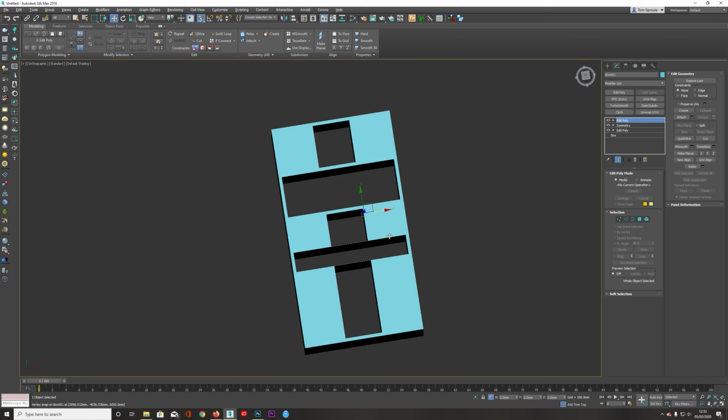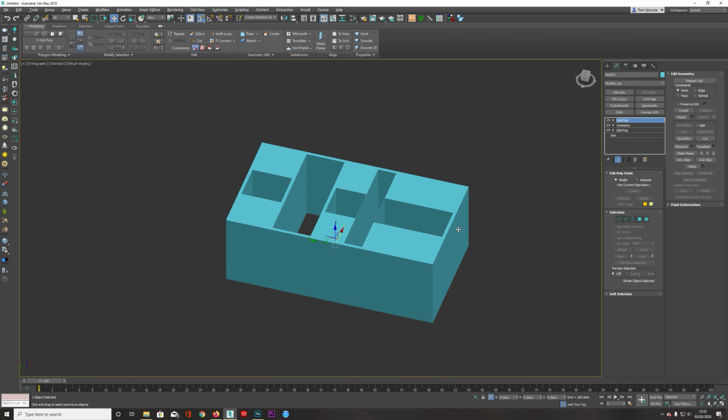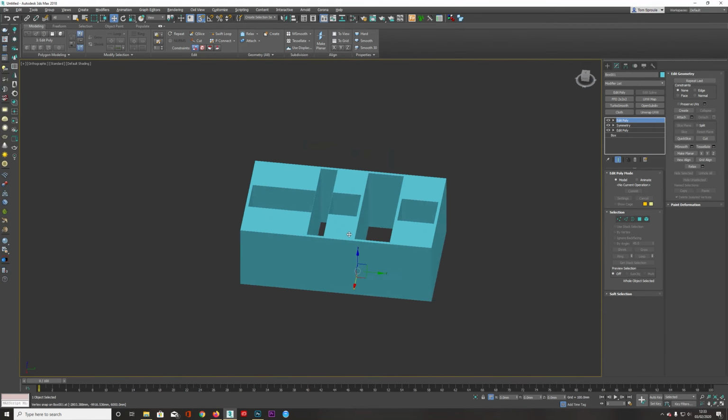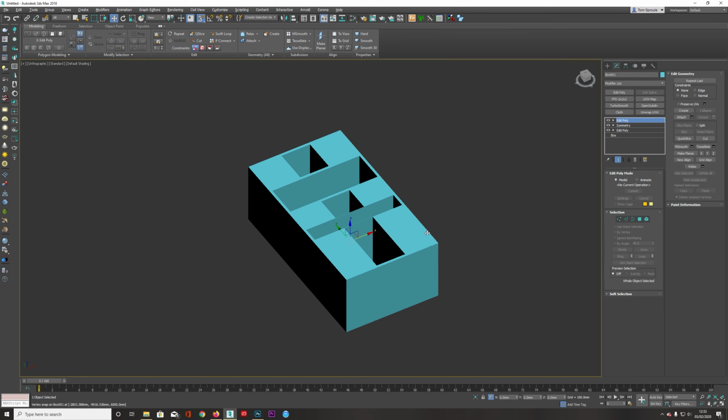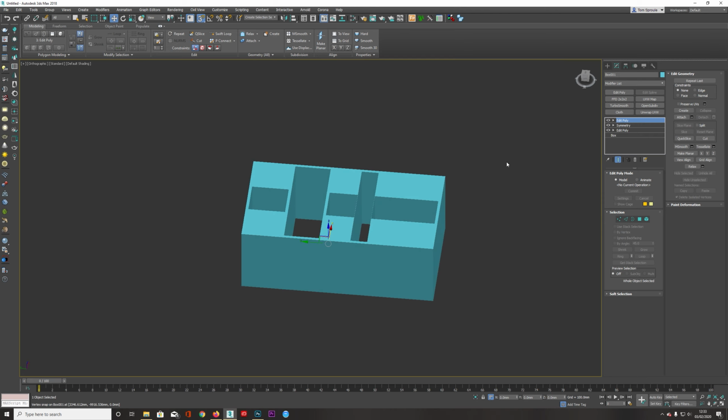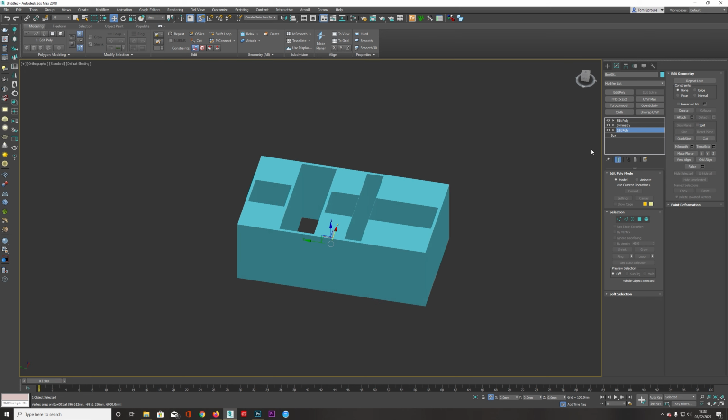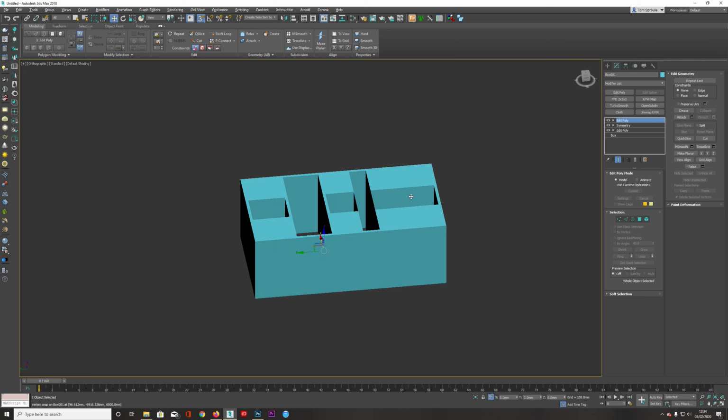Okay. So let's throw these doorways in, and I'm going to throw these in before I put that symmetry on. Actually, I'm going to have to redo the edit poly if I do. Because if I come back here and start working on the scene, basically these vertex will have different numbers that I moved, so I'll have to move those again. So I'm just going to come here, and I'm just going to right click and collapse to.